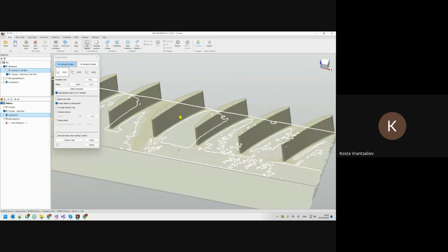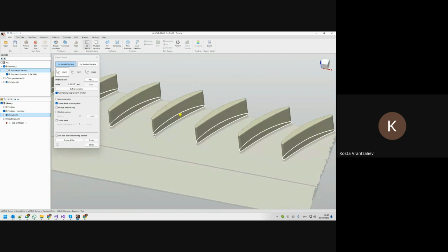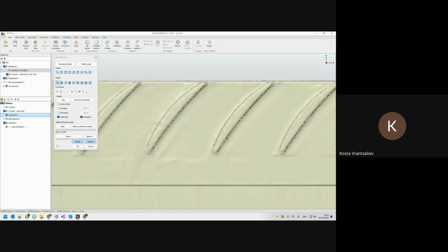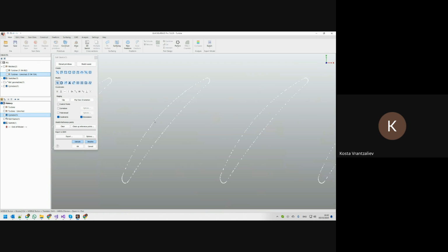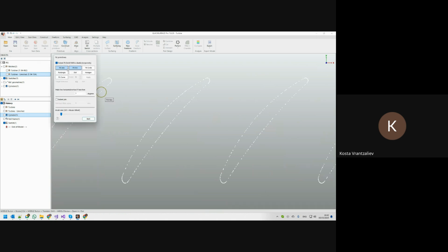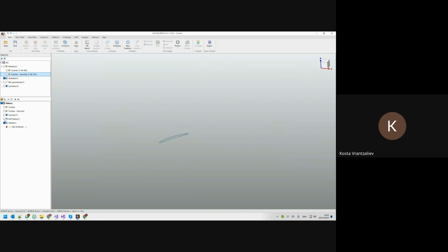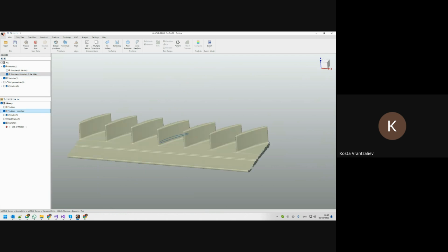Again, you can just take this cross-section here and create this sketch only on this one. But now instead of just drawing, I can fit an arc here and fit another arc here very accurately, because this is what we always think about: design intent. Now if I just press OK, I have this one single 2D sketch.